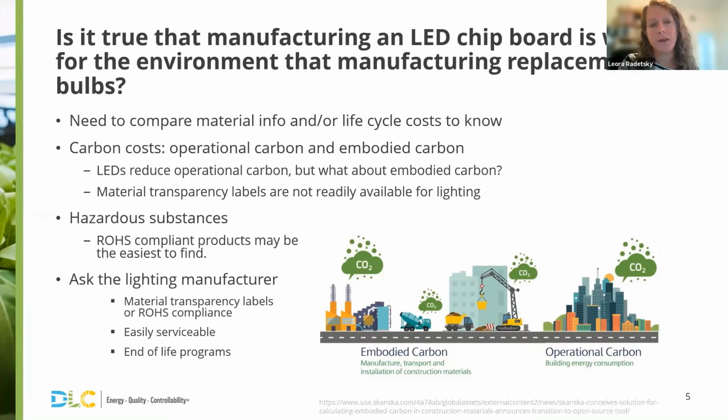The nice thing about RoHS compliance is that it has been rolled into the CE marking as of 2011. So if you see a CE mark on the spec sheet of a manufacturer, it's good to confirm that that also means RoHS compliance, but it's pretty likely that it does. That's a good way to see if there's less hazardous materials in that product. And that's something to also look for. So I think that's an easy thing to ask for and an easy win.